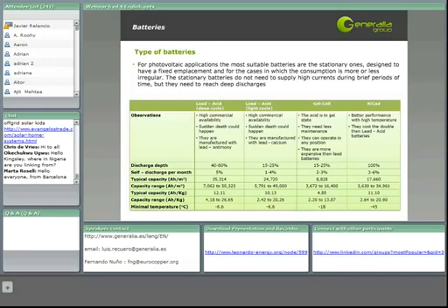Normally we have to know that gel cell batteries need less maintenance and can be operated in any position, so they are normally used, for example, in applications of traffic lights and for illuminating the city, but they are much more expensive than the lead acid ones. So for normal commercial applications we will use lead acid types.